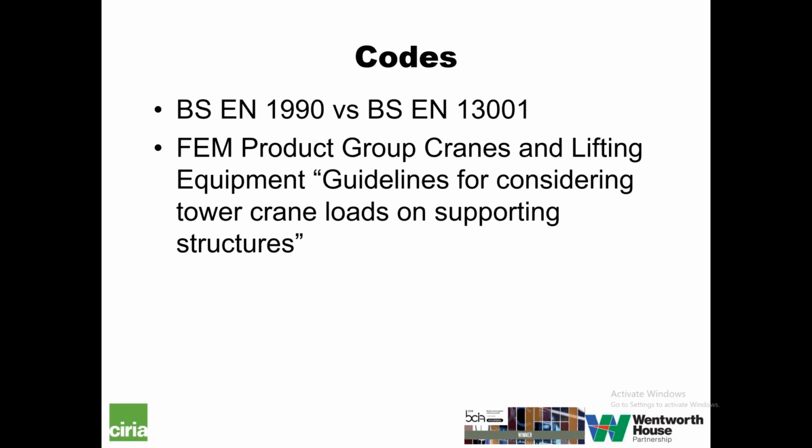So the first challenge was to try and reconcile those issues, and the FEM, which is the European Materials Handling Federation, which includes the tower crane manufacturers, produced some guidelines which were helpful in untangling these load factors. And we have basically adopted those guidelines rather than the basic Eurocode load factors.